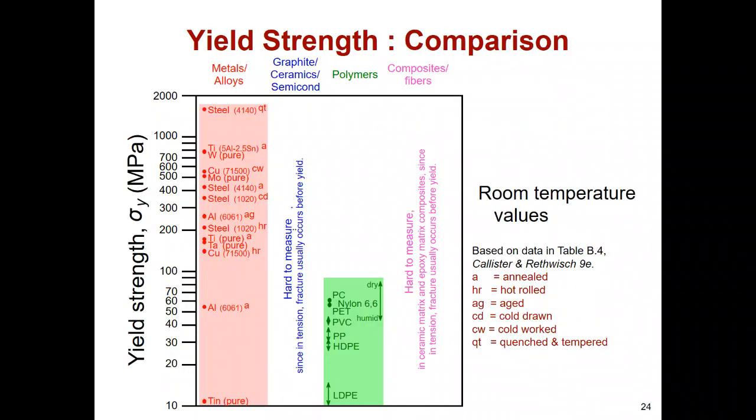So the yield strengths can be tabulated in this slide. Metals and some structures will show very high yield strengths, but polymer structures can easily be expected to have very small yield strengths. But there are no yield strength data for the ceramic structure. Do you guess why? It is because, as I said a few months ago, the ceramic structure consists of very strong covalent bonds.